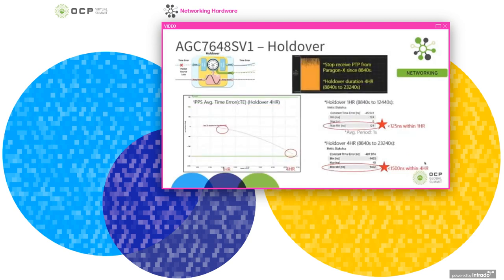And for another one is the hold over test. You can see when we stop the packet transmission at around 9,000 seconds, it could still keep within 125 nanoseconds in 1 hour, and within 1,500 nanoseconds for 4 hours.